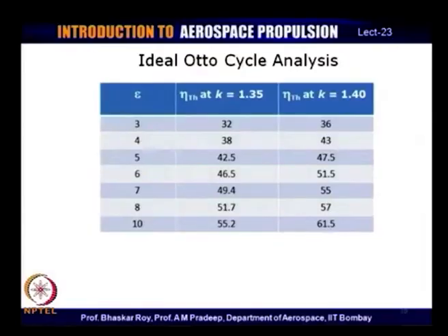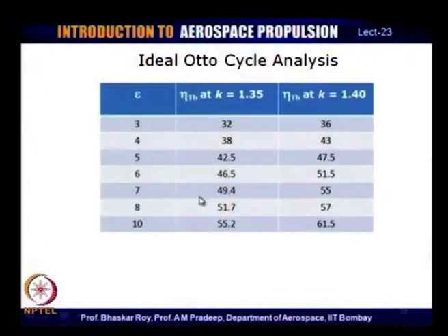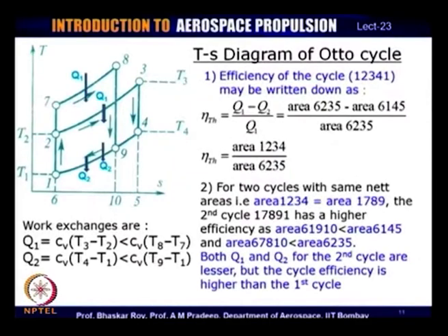What the compression ratio can be depends on a number of parameters or practical considerations, and we shall be talking about some of that as we go along in this lecture and in the next lecture. So, the cycle designer has an idea now that if he chooses a certain compression ratio, and given the working medium, he would be able to attain a certain cycle efficiency, which he hopes to come pretty close to in an actual working engine.